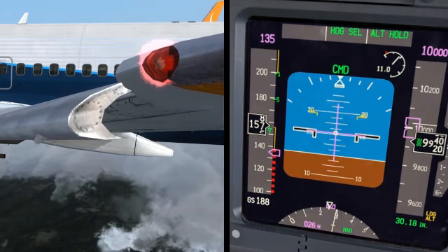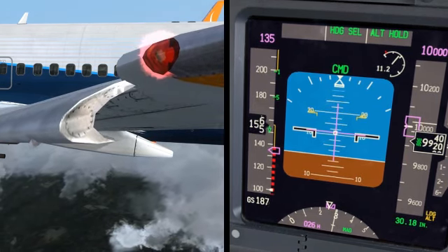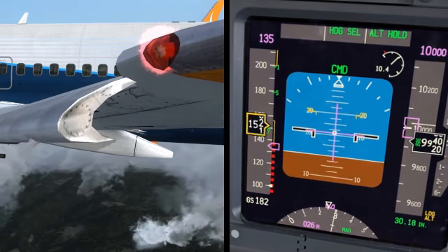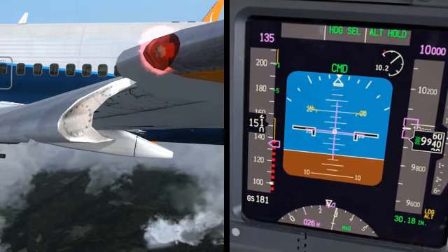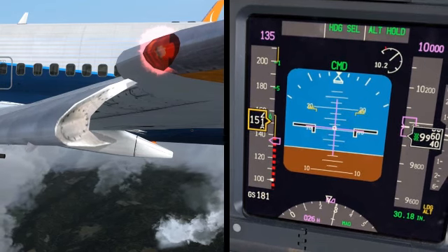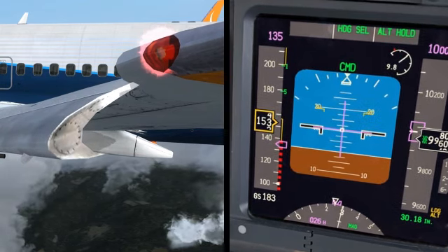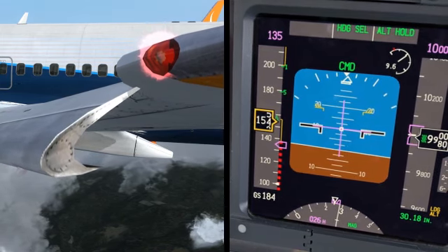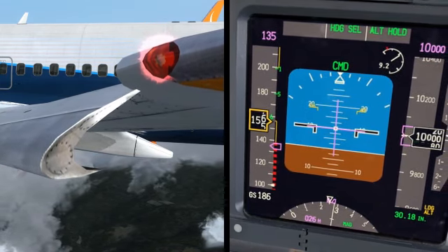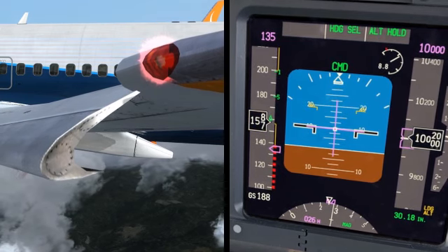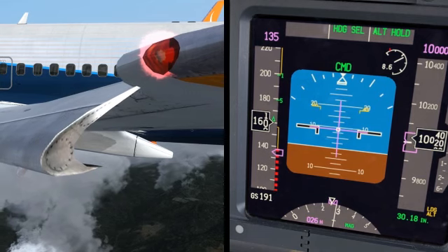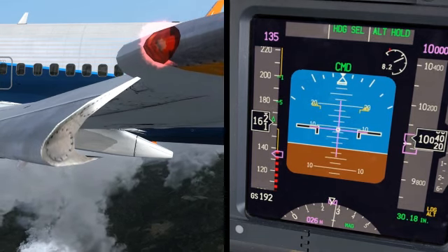This feature is only available when the flap lever is in the 1, 2, or 5 detent. However, there is an optional package for short field operation that activates this system when the flap lever is in any of the previously mentioned positions, or the 10, 15, or 25 detents. The leading edge slats return to their normal extended position when the stall condition has been prevented by decreasing the nose-up attitude.